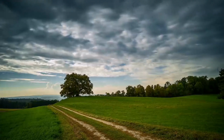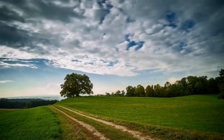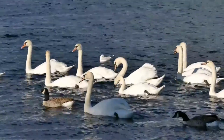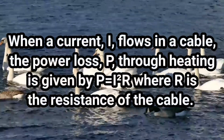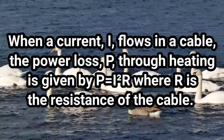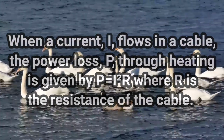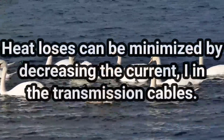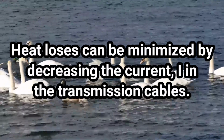And again, before I say goodbye, let us do the checking on what knowledge you should have achieved after following this lesson. Number one, when a current flows in a cable, the power loss through heating is given by P equal to I squared R, where R is the resistance in the cable. And the heat losses can be minimized by decreasing the current in the transmission cables.